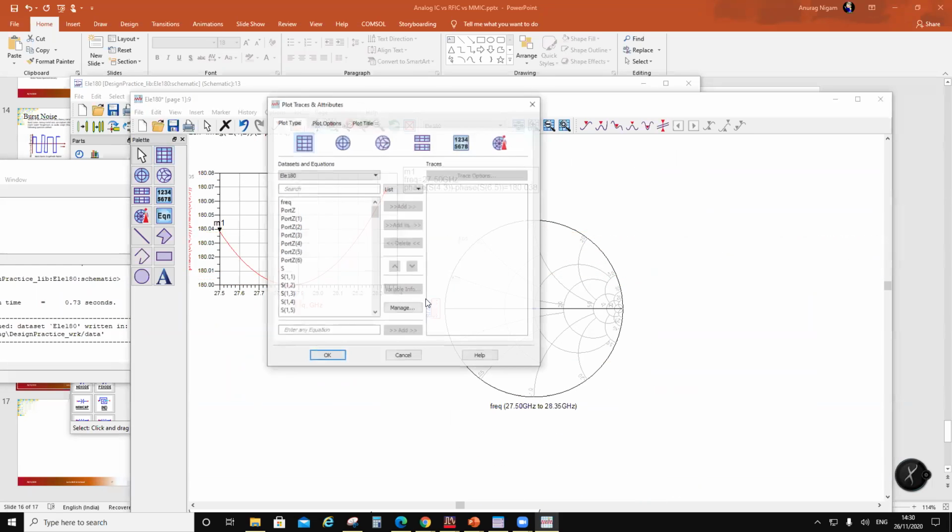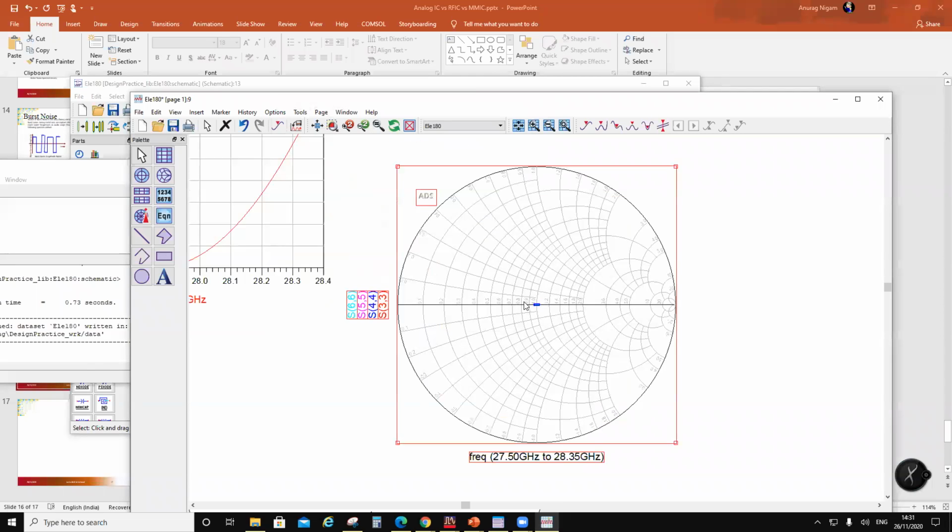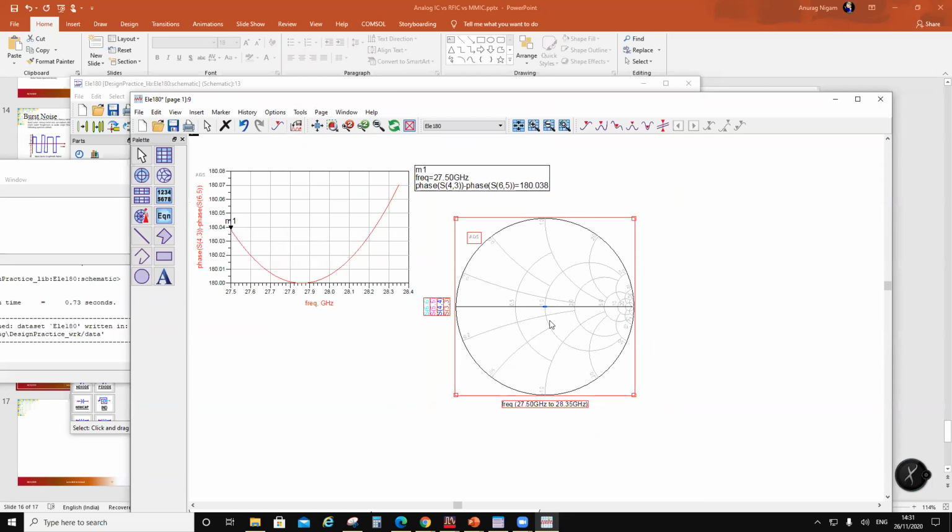What about the insertion loss? I want to look at in both paths whether I have the same insertion loss. S33, S44, S55 and S66 also I will see. S55, this is going to be the low pass element. S55 and S66. So I'm looking at the 50 ohm match. Everything is at the center. So really it is not a problem of matching here.